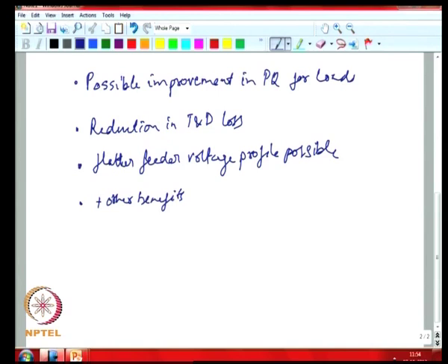So, you need DG systems where you can limit the fault current when there exists a fault and not have significant difference in fault current levels when you add the DG unit. Also, we saw that some of the equipment might need to control the power flow at different sections of the feeder in an accurate and fast manner depending on the existing load power flow. So, you need fast power control, and you also need the possibility of very rapid switching.